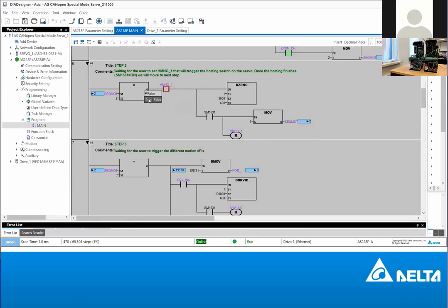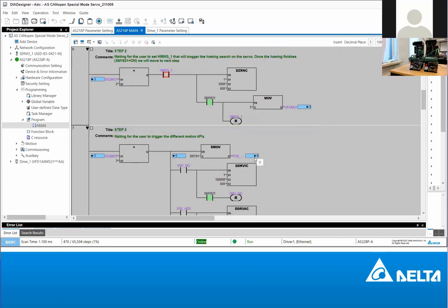So let's perform the homing. If you check the video, you can see that the data logo is not well positioned, it's vertical. So after I've done the homing, the data logo should be well positioned such that you can read it correctly. Let's see if that happens. Let's perform the homing. You can see there was a rotation. You can see the data logo now you can read it normally. Now my drive is home. And that is position 0. So from this reference point 0, you can move your drive to any displacement depending on the kind of machine you are making.